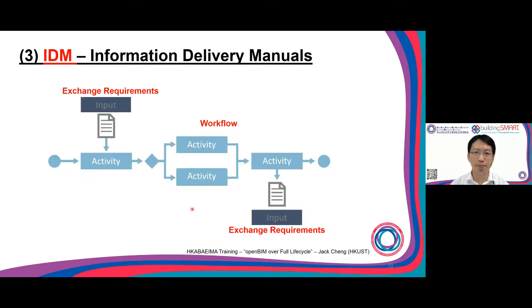Then we have IDM. IDM basically is the information delivery menu. There are 2 main concepts for IDM, and later we will also touch on that again. One is the workflow, another is the exchange requirements. Workflow for IDM is basically the whole workflow, linking all the tasks together. And then for each task, we need to specify who should provide what information at this task and who should receive the information as well. So that's why IDM is basically the workflow and then the exchange requirement for each.